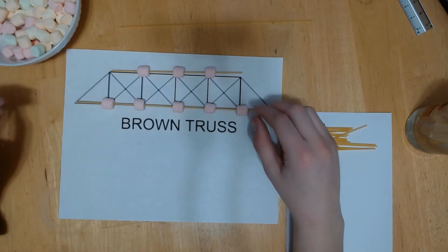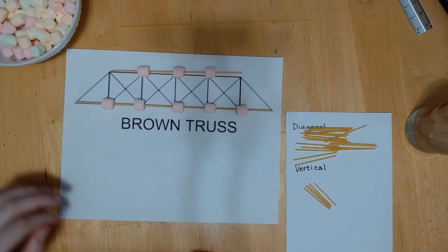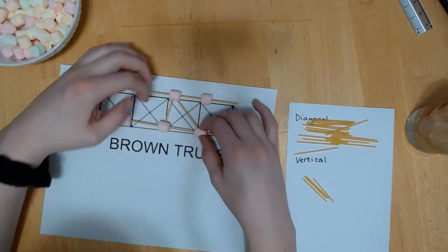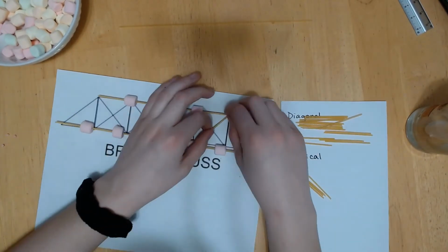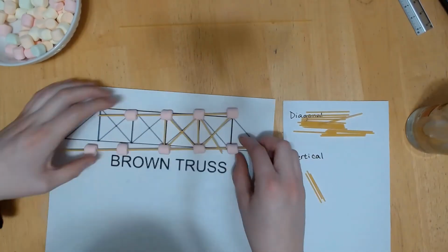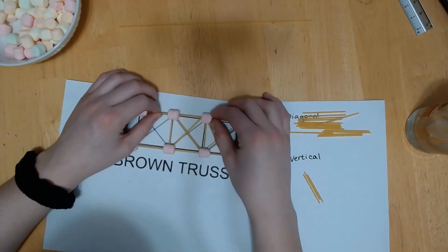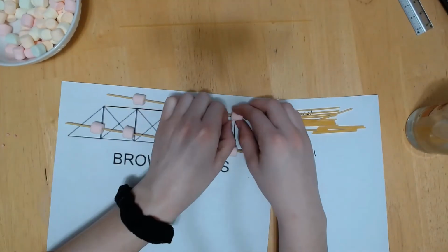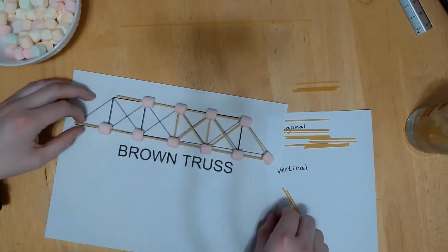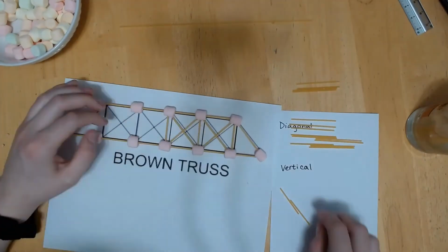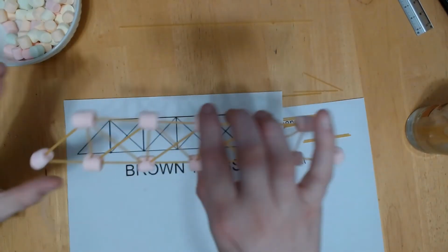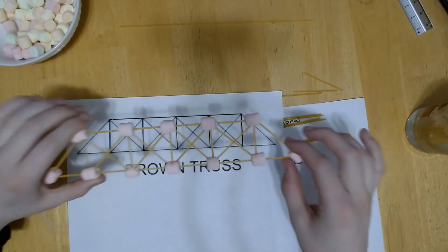Okay, now that we have all of the marshmallows on our main beam, it's time for us to finish up the rest of the walls of our truss. Snap off enough pieces of pasta to complete the interior, vertical, and diagonal portions of the truss, and then attach them to the marshmallows. Your truss wall will get more rigid as you build it, so as a general rule, I like to attach my supporting pasta noodles starting at the center and then working out to the sides. You can always use your template as a check to keep your connections straight. Okay, that looks pretty good. I'm going to speed up the footage while I build another identical wall for the other side of the truss.